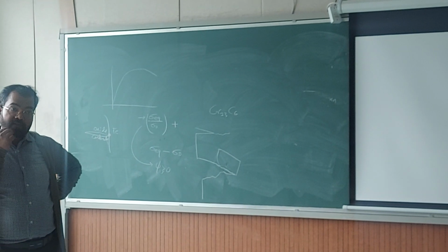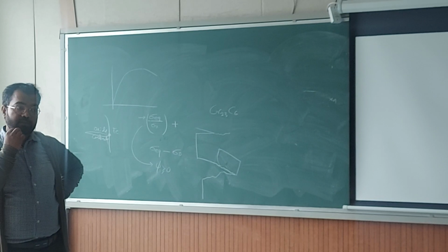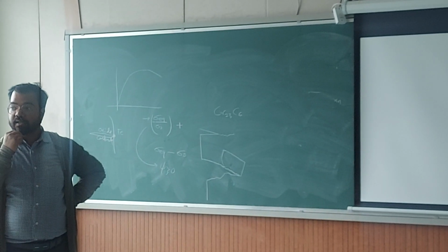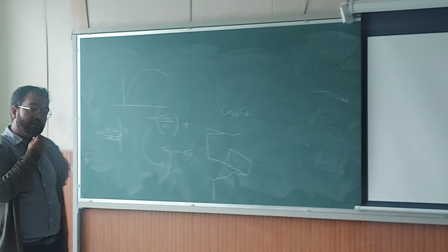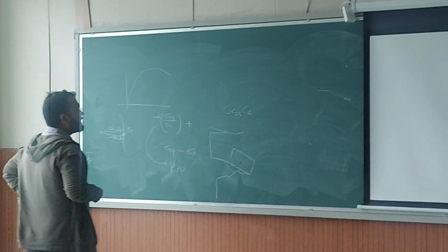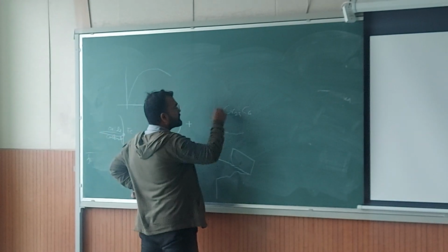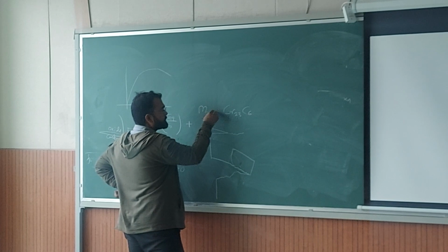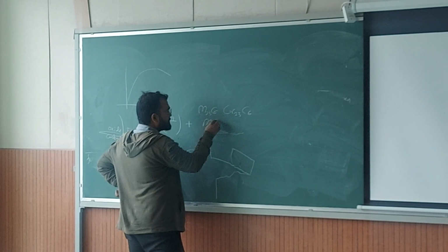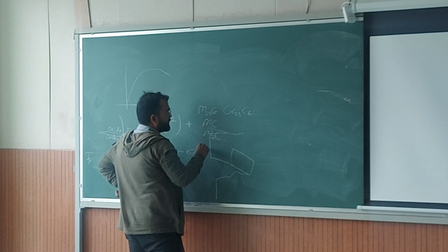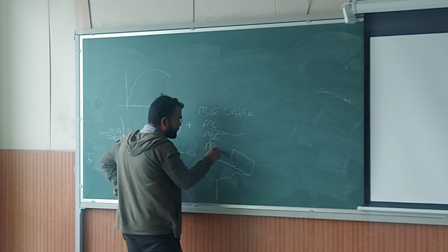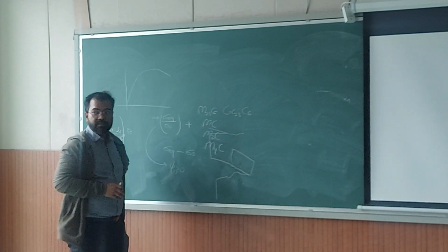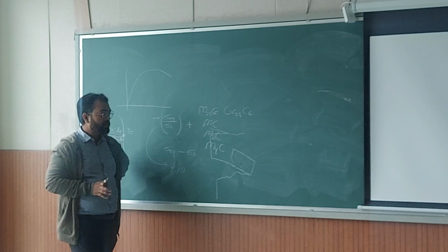So you will still have lath features if the martensite was lath, plate features if it was plate needle, and all those things. Okay. So you have different types of carbides. So this is generally known as M23C6, and then you have MC, M2C, M4C, and different elements form different types of carbide.